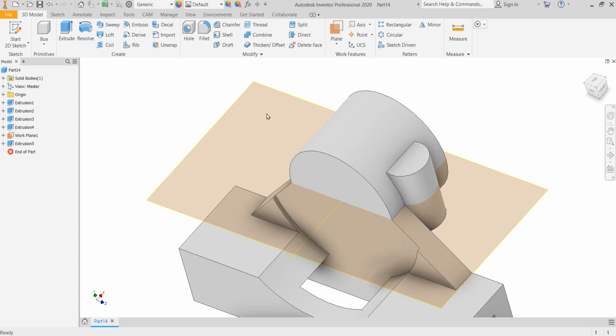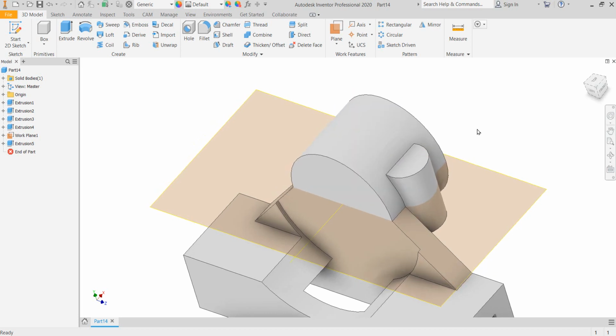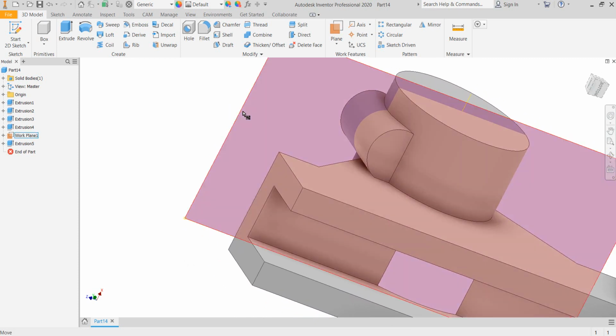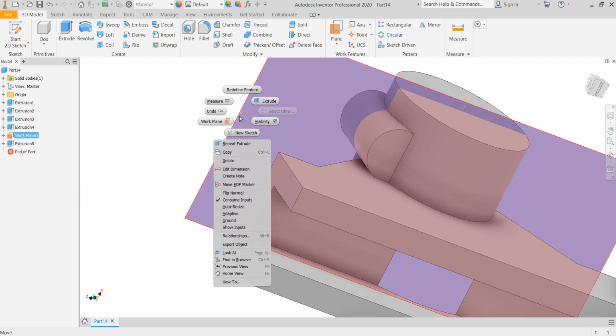And the book shows a cut coming through the cylinder here. You could certainly put it in now. However, having built this thing several times, it will cause you problems later when we go to fillet this part. So I'm going to wait about putting that cut in until I'm working in the individual part file and I've already filleted this thing. But there is a cut on the bottom that we can do. And so I'm going to hide this for right now.